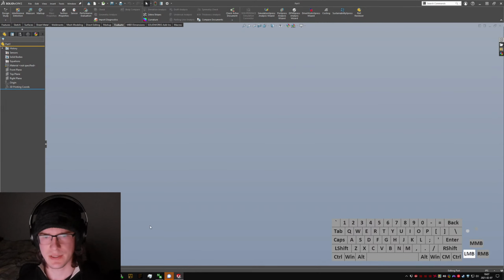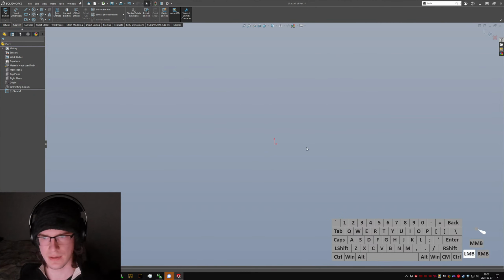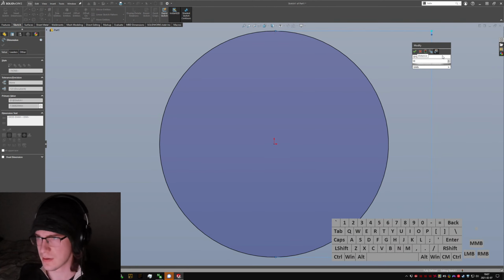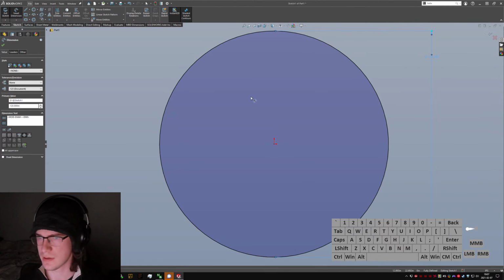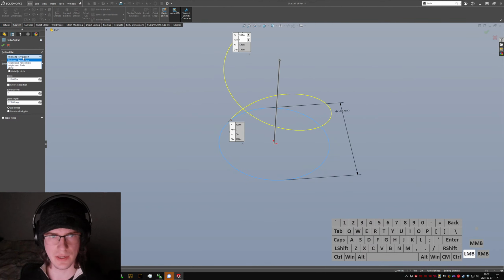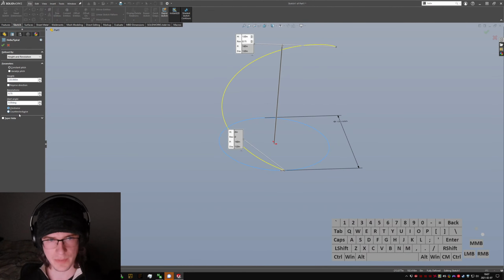So let's go ahead. I think the way I want to do this is probably helix. So we'll start off with that, start with the top plane. I may end up drawing 2 helices just because it seems like it'd be, let's see, 10 feet. Okay. Let's see, pitch and revolution. Actually, I know height and revolution. I know that it's going to be 10 feet tall. And we know that it's going to be 0.75 revolutions, fortunately. And start angle, let's see, where does 0 put us? Clockwise.